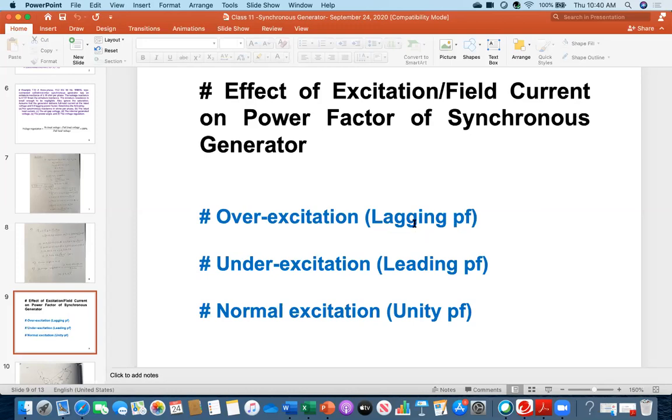So this means when customers are using much more lagging power factor load, the power operator or generator should generate high voltage at the expense of overexcitation. This means this is a lossy system. Now, if customers use the leading power factor, and their loads are mainly capacitive, then you need to produce less voltage. The generator needs only a small excitation, which is called underexcitation. That is the meaning. So now once again go back there, and you will have much more fun.